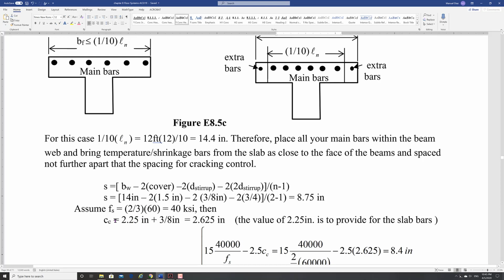And the C sub C again is with the 225. Don't forget that. So you have to put the stirrup, right? So you need all that in order to fit it in there. You don't calculate that. I mean, you're going to have your stirrups right in the middle of the bars, right? So those are things that you have to think about when you're doing the detailing.